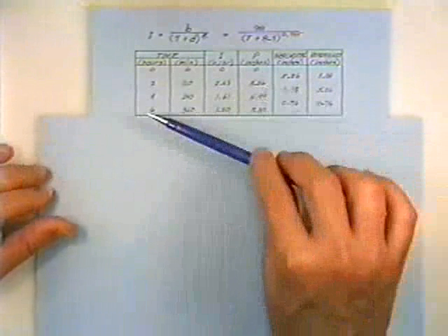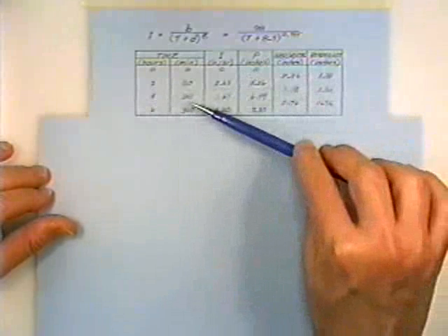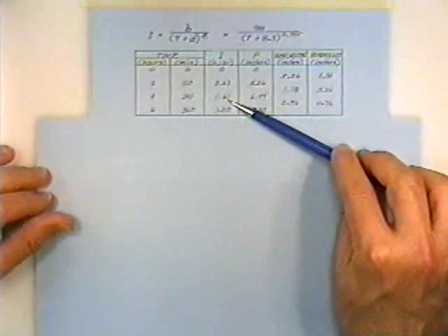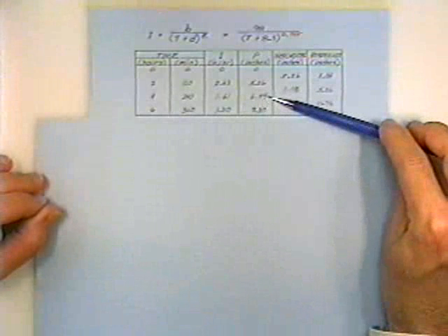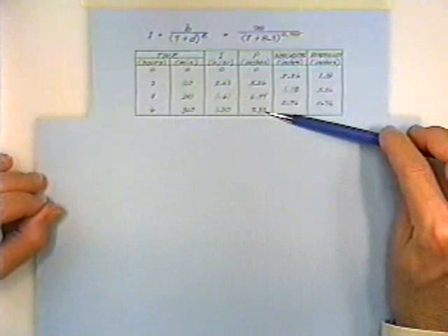If it rains for 4 hours, you're going to get more rain, so we plug 240 minutes in, that's 1.61 inches per hour, times 4 hours is that total volume of rainfall. Now, if it rains for 6 hours, we'd get that total volume of rainfall.